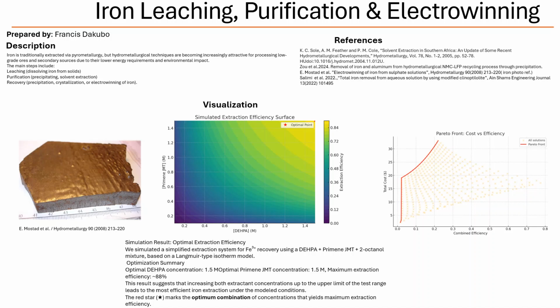And you need to stir things up, right? And maybe add some jarosite seed to help it along. Yeah, that helps to get those nice well-formed crystals. The downside is that other metal ions like copper, zinc, cobalt, nickel, manganese, even some less common ones like indium, gallium, and germanium, they can get trapped in the jarosite crystals.